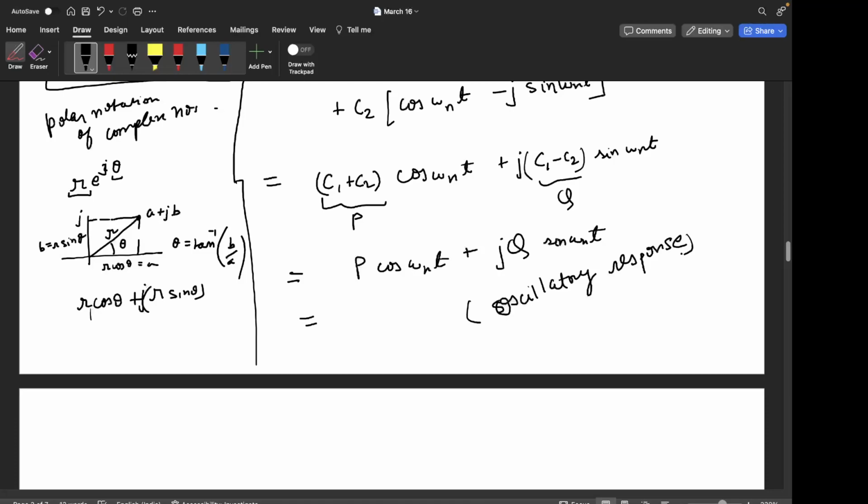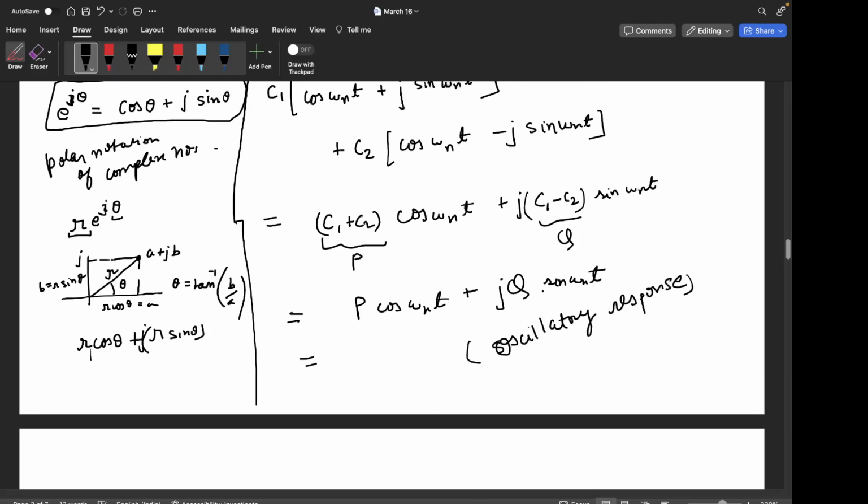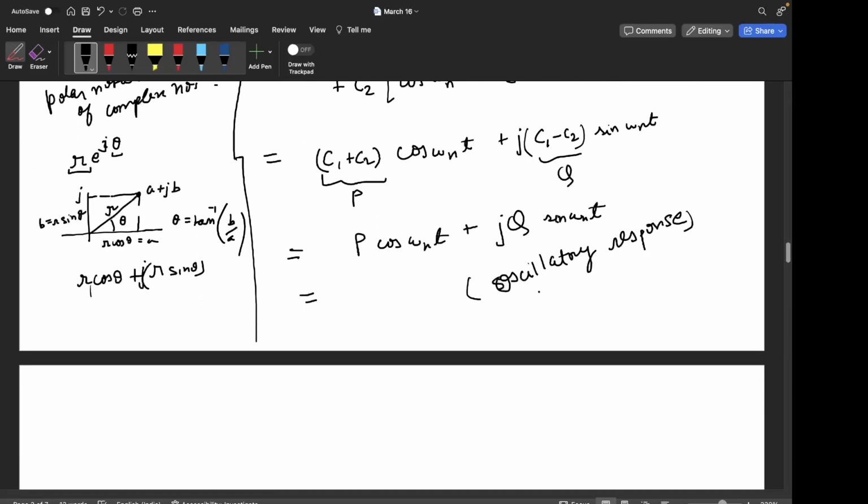And now you can express these in multiple different ways. You can express the whole thing together in terms of a single sinusoid, something like this: A cos(omega_n t + phi). There is a very standard way to express a sinusoid. So natural frequency is omega_n, phi is the phase shift, right? A is the amplitude.